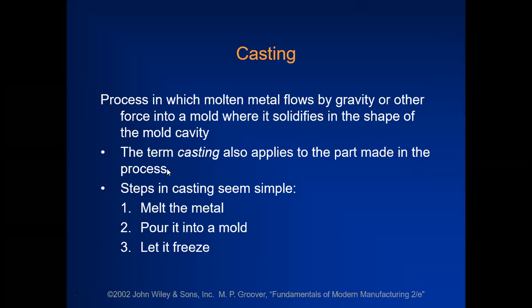First of all, the metal should be melted in the furnace. Then the molten metal should be poured into the mold with the help of a ladle or any other means. By the end, we let the molten metal freeze, to solidify.